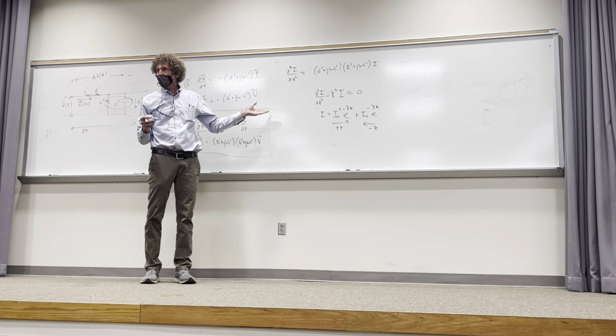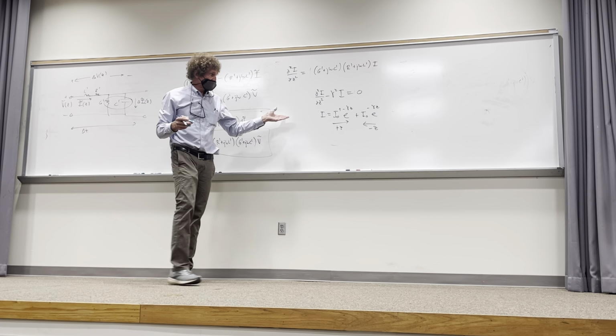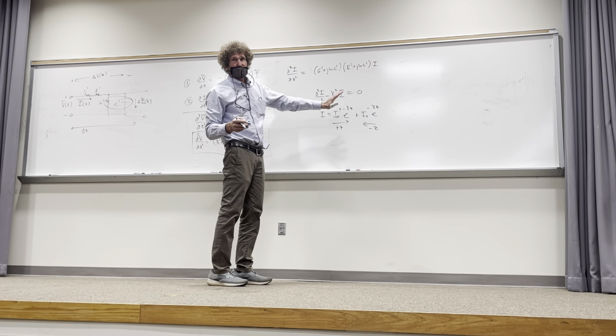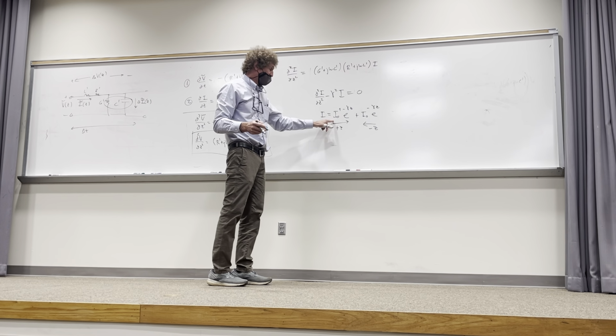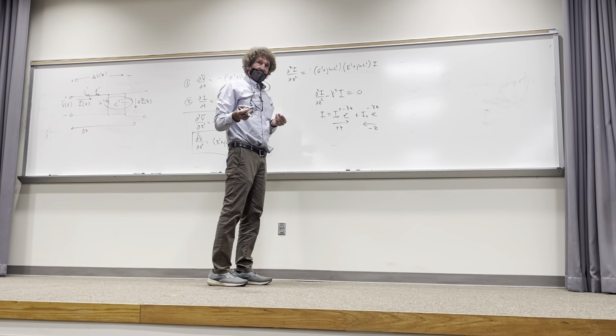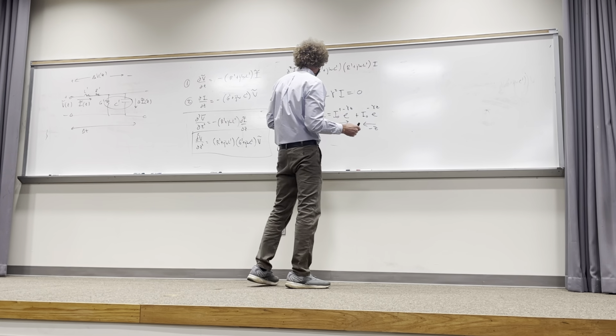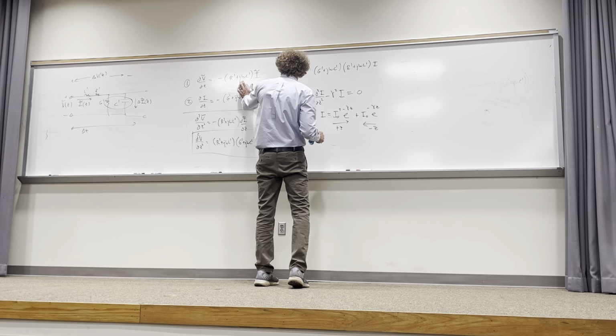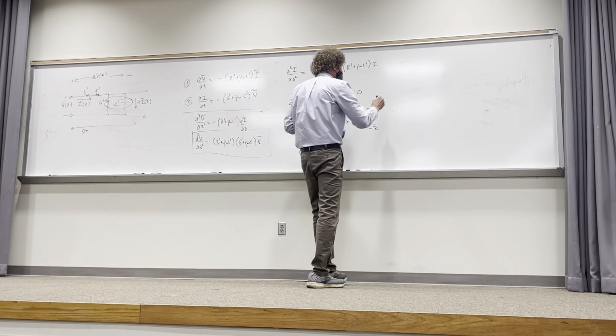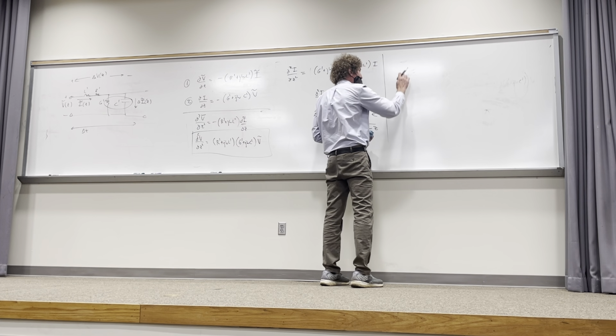Now, when you do this, I'm not going to put the time domain form. It's identical as before. It's just instead of V, you're going to have these I's here. Now I'm going to find the relationship between I and V. I'm going to start by looking at this equation, and I'm only going to look at the positive traveling wave, or else these things get a little lengthy.